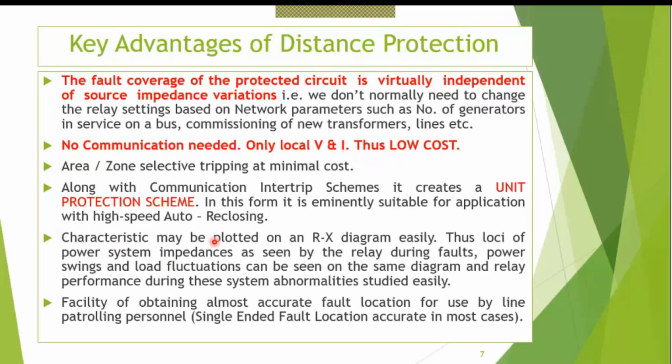The characteristic of a distance protection may be plotted on an RX diagram very easily. Thus, loci of power system impedances as seen by the relay during faults, power swing, load fluctuation can be seen on the same diagram, and relay performance during all these system abnormalities will be studied very easily.